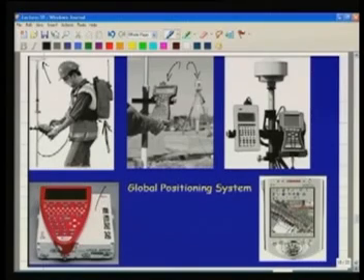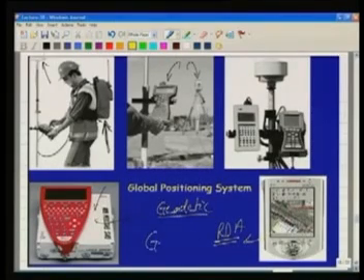Also, this is the Leica GPS, which is used for geodetic surveying, or it is called a geodetic receiver. Geodetic means it is very accurate, while the GPS data can be put into a PDA, and this PDA can be connected to another receiver which is handheld, and we can carry out mapping, as we can see over here, over GIS data, over the existing data.